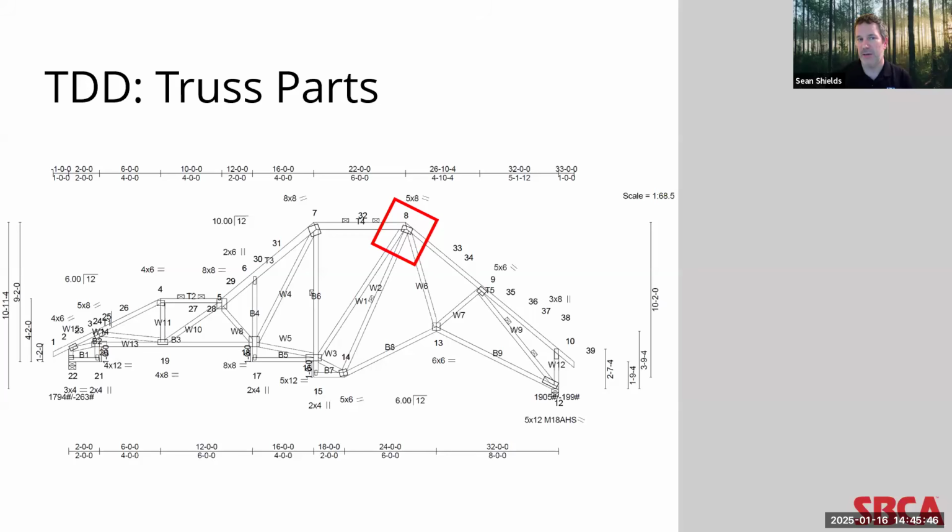But when the truss designer is designing a particular truss, sometimes a smaller plate size may or may not work. So, for example, they may have a truss designed where a 3 by 5 plate would work just fine, but they only have 3 by 6 plates in stock. Again, 3 inches high by 5 inches versus 6 inches wide.